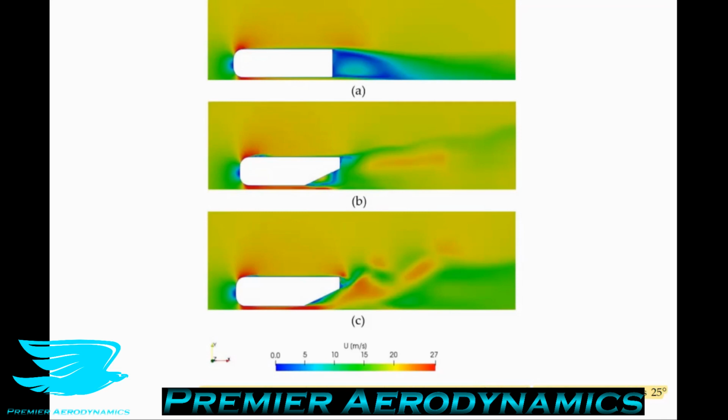What about when we put the vertical airfoils on this armored body with the 25-degree diffuser? When we do that, we can see that the wake drops even more, but there are some slight differences in the flow separation. There's a little bit of flow separation around the start of the diffuser and around the back of the armored body. And then the flow, you can see, is pushing up at a much higher angle.